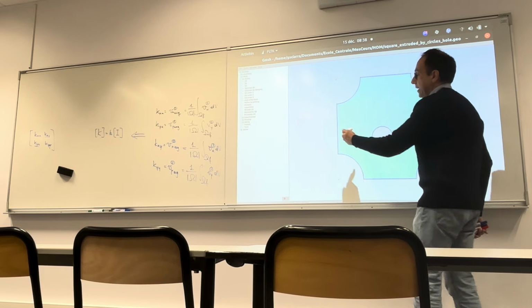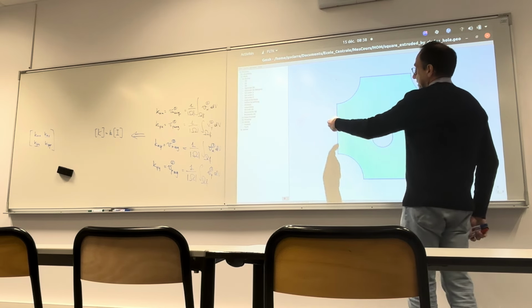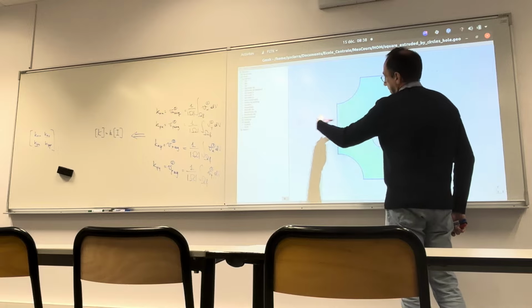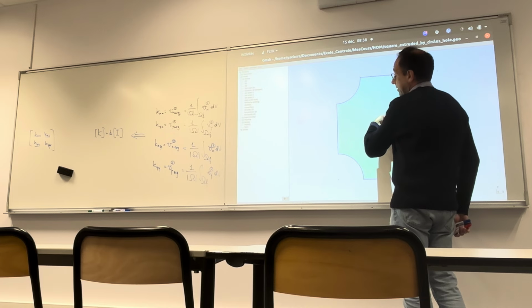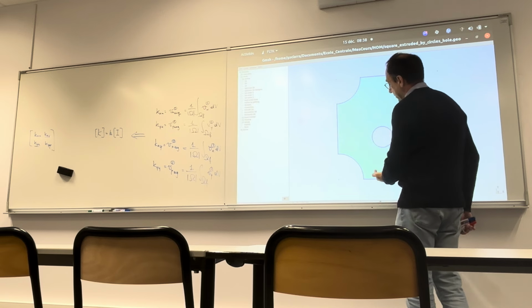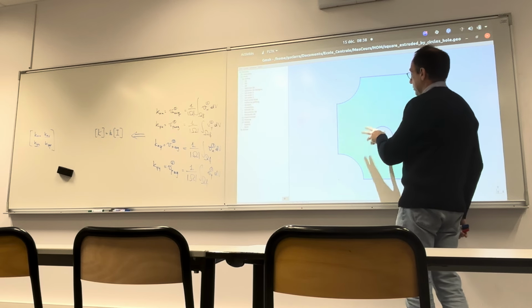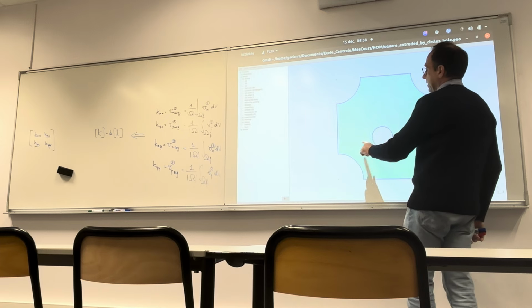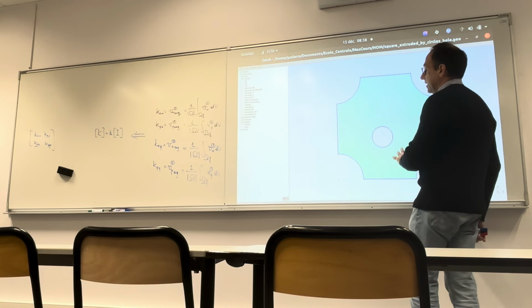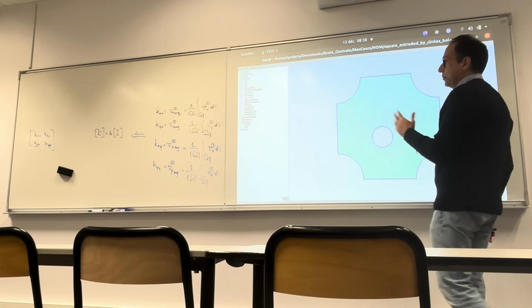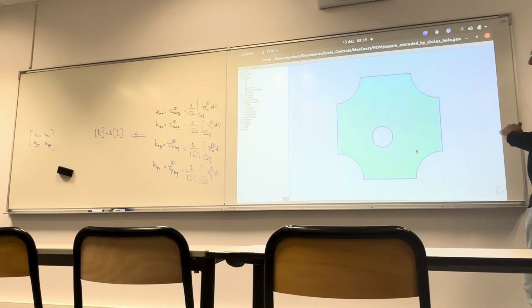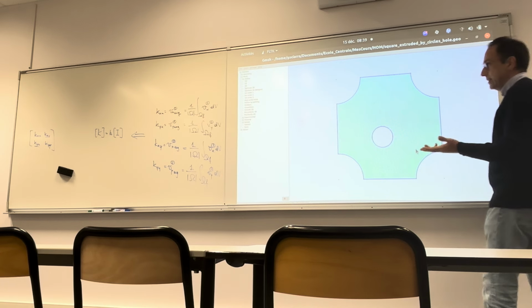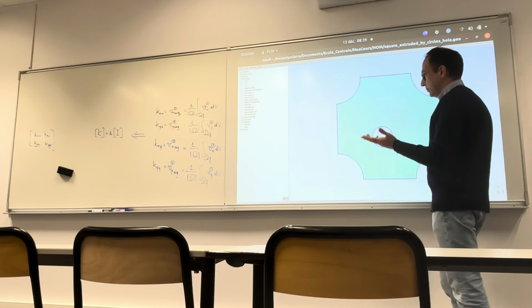Because essentially you are considering the same problem with an E1 unit force or an E2 unit force. So if the two configurations are equivalent when turning by 90 degrees, you could get a different KXX from KYY, but you will get the same KXY equal to 0.